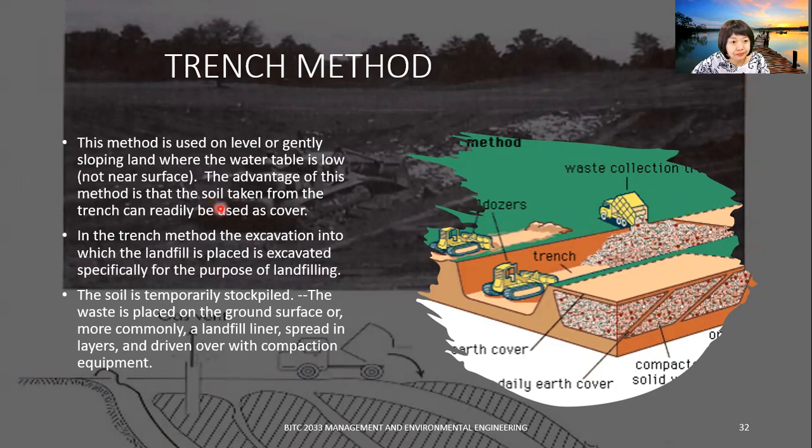In the trench method, the excavation in which the landfill is placed is excavated specifically for the purpose of the landfill. The soil is temporarily stockpiled, so the waste is placed on the ground surface or, more commonly, on a landfill liner. And then we spread it in layers.